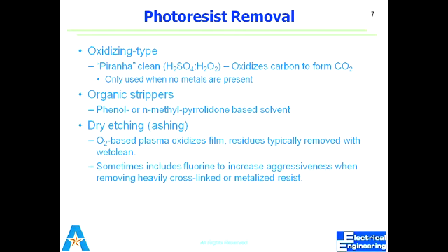So I have a question. For a specific photoresist, can we use any method? Okay, not for a specific photoresist. It depends upon your application. As I told you, dry etching cannot be used everywhere. If I want to etch something and I want a pattern with sharp edges, this cannot be done with wet etching. I will have to go for dry etching. So it depends upon your application, and then you decide which etching process you need to use.